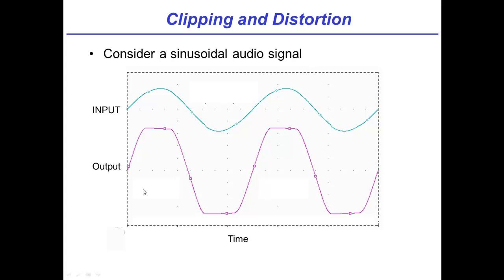Now, here's the key point. To create that sum of sinusoids, they now cover multiple different frequencies. Because, for example, wherever you have these sharp edges, they will indicate that you'll have some very high frequency components built into it. So what happens, you're saying, is that where I was hearing a nice, pure, beautiful 8 kilohertz tone, my speakers, after I ran it through my amplifier and then ran that through some speakers, it sounds like a repeating pattern, but with some distortion, with some weirdness to it. Right. What you might hear is 8 kilohertz and 8.3 and 9 and 11 and 15 and who knows. Okay. Because it's whatever sum you need to create this shape. Right. And the ear will perceive that as distortion because it's non-harmonious.